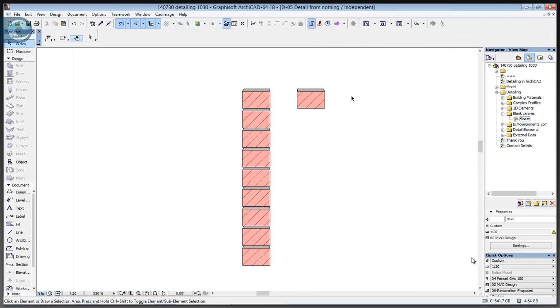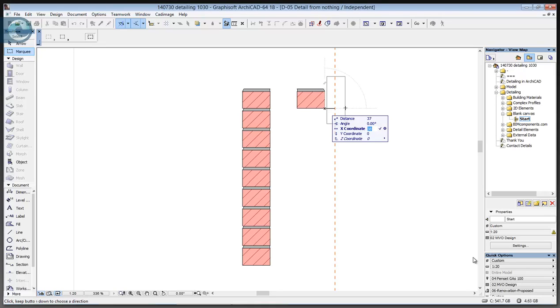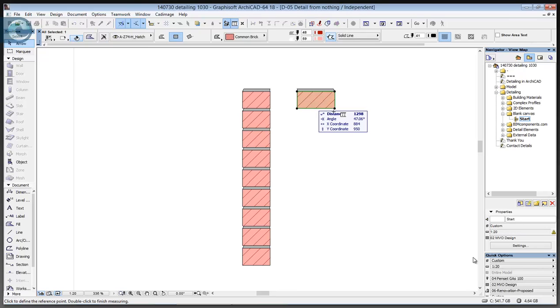So that gives me a 102.5 sized brick. But what I want is actually a 140 wide block. So I'm going to take a marquee, stick the mouse there, and go from there X37.5 plus. And what that does now is stretch that end so that this is now, if we go and measure, there to there, 140 mil wide.